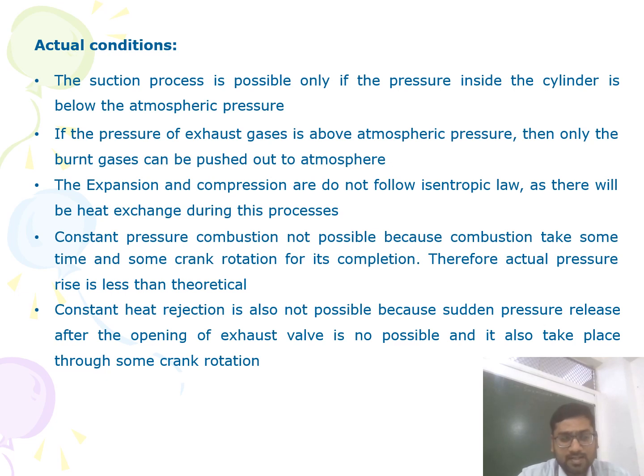Last assumption, in the same way: constant heat rejection is never possible, because a sudden release after the opening of the exhaust valve is not possible, and it takes place over some crank revolution. So combustion, heat supply and heat rejection processes require some time. An instantaneous process never occurs in nature, so that is the actual scenario in this engine.